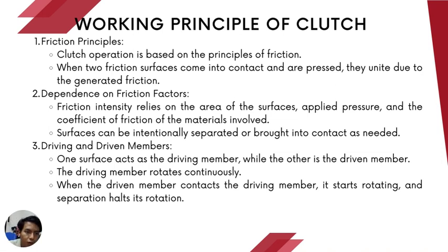Next, I have marked a few points on the working principle of clutch. First of all, the friction principle. Clutch operation is based on the principle of friction. When two friction faces come into contact and are pressed, they unite due to the generated friction. Second, dependence on friction factors. Friction intensity relies on the area of the surface, applied pressure, and the coefficient of friction of the materials involved.